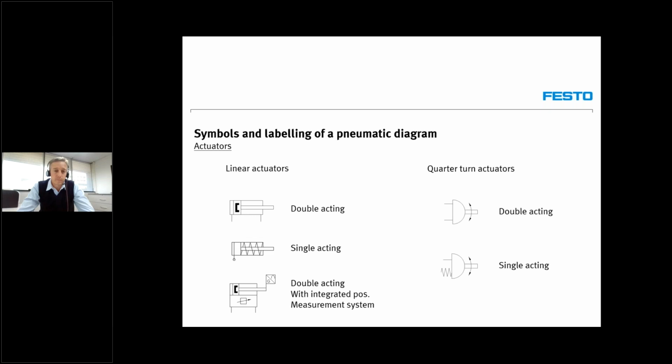Yeah. Hannes, there's a question asked earlier on. I think the person may have left, but let's just tackle it anyway. I didn't fully understand the question, but he was asking about the difficulty of using the manual drain, and I suppose maybe the frequency of using it, and are there any other options? I know collectively in the team we have a fair amount of experience here. If I can kick it off by saying that often what we used to do is remove the manual drain screw and put in a more robust type of ball valve, or connect it to a very robust type of solenoid valve to purge automatically after a while.